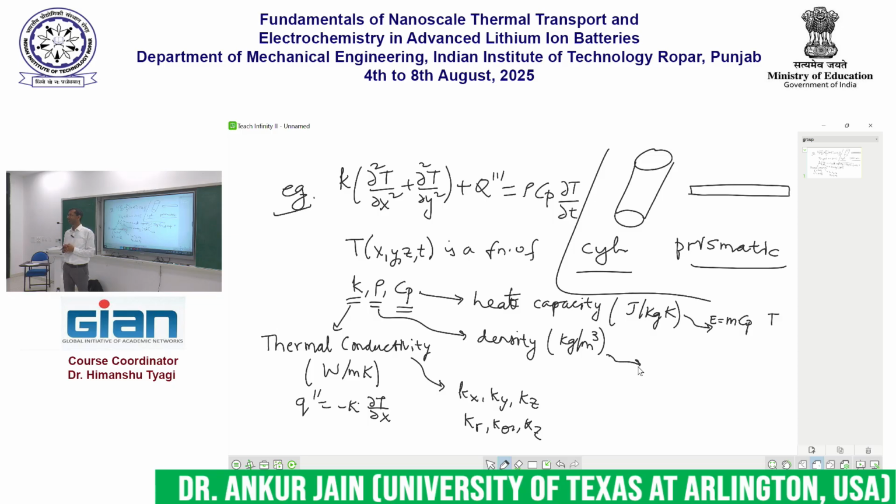What is the density of water, for example? About 1000 kgs per meter cube. Typical metals are higher than that, plastics and polymers lower than that, gases even lower. For air, the density is of the order of only 1 kg per meter cube. Somebody comes to you and says, I have a material with 100,000 kgs per meter cube. You need to say, slow down, something is not right. A feel for numbers is extremely important.